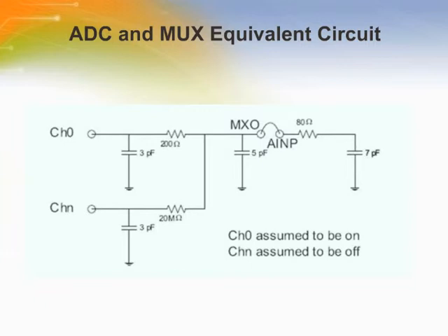The current into the ADS79XX charges the internal capacitor array during the sample period. After this capacitance has been fully charged, there is no further input current. When the converter goes into hold mode, the input impedance is greater than 1 gigaohm. To maintain linearity of the converter, the CH0 to CH-end and AINP inputs should be within the limit specified. Outside of these ranges, converter linearity may not meet specification.